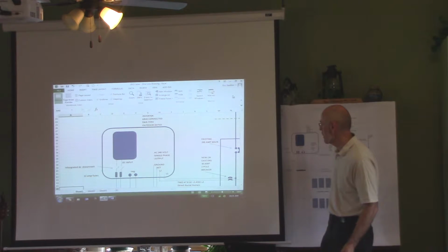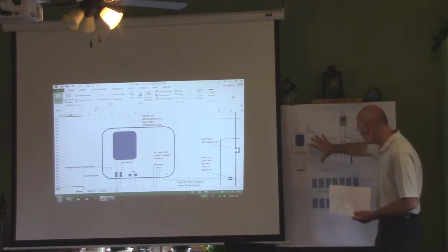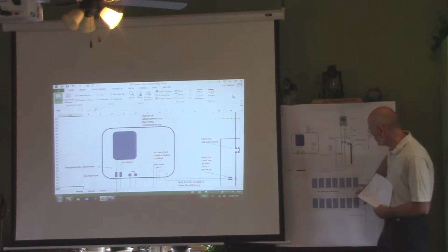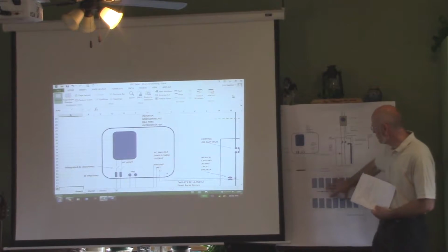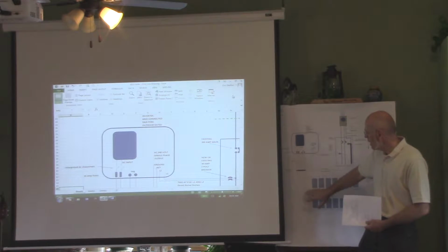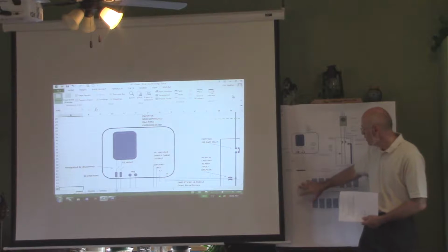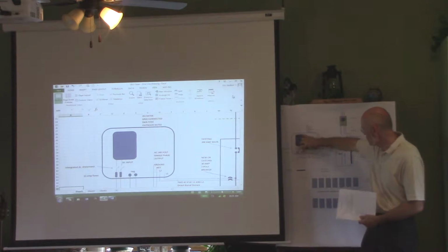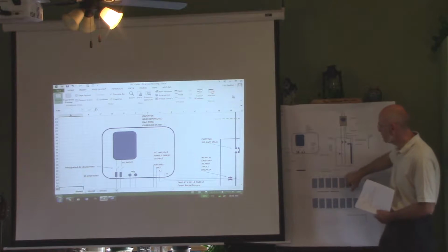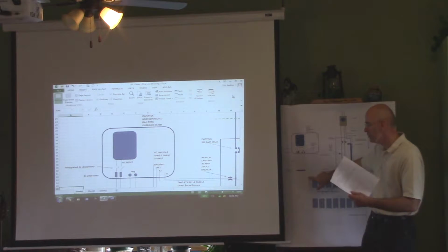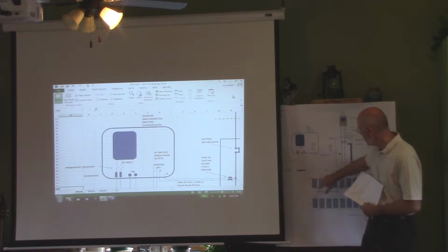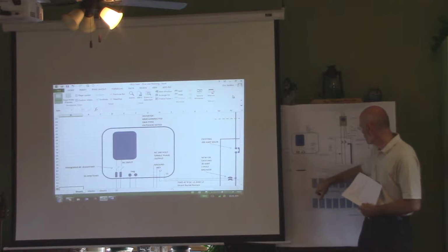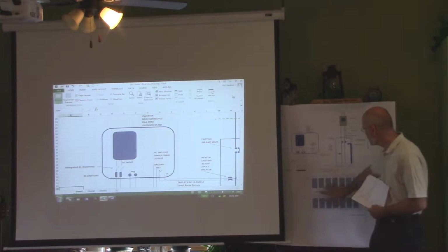Okay, so I'm gonna transition into what this system is. This is what's called an on-grid system. We're gonna walk through this. We've talked about the panels and how to build up the voltage. We've talked about having the wire the right size and the current, making sure that the inverter is happy on the DC side. So what we're doing here is we're connecting each of the solar panels together to get the voltage up. Now we've got 270 volts or so, and we're at around 15 amps as a total coming in.